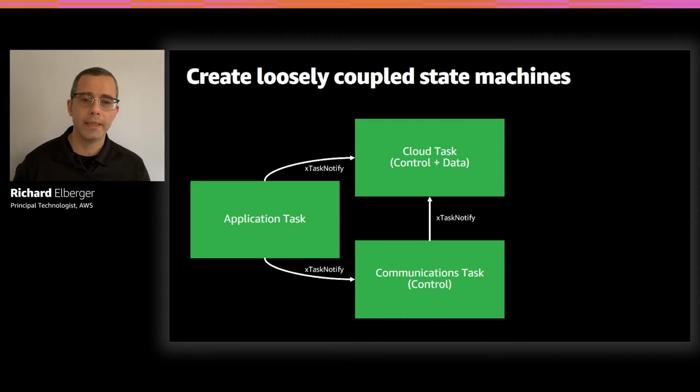We're not connected to the cloud yet. We're still in the communications task. We need to create that TLS 1.2 socket connection to the cloud. We're walking our way up the OSI stack. We need the endpoint, or the DNS address, of the server that we're connecting to in order to make the socket connection. When the socket connection is done and we're connected to the cloud, we're ready to start sending and receiving data. This task also owns the buffers for the communication, so we have proper encapsulation when we're doing this. Now we're ready to move on to the cloud task.